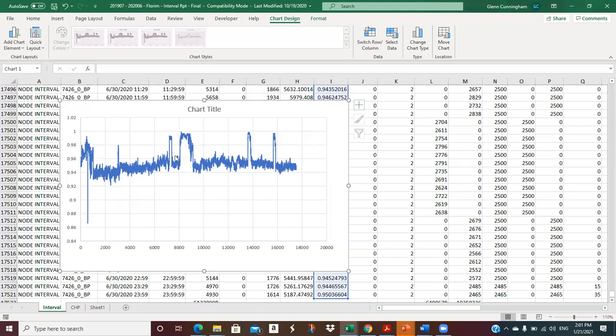And you can look across here, with information like this, you could divide it up into months and you could see what you thought their billing demand was going to be. And then you could say, well, how much do we think we could really save on this? But 95 is right in here. So they're spending most of the time right about 95. So it doesn't look like they've got a whole bunch. That's probably better than most places. If you're not doing correction, it's probably not going to be. This may be when capacitors kicked off or something. That probably is. They probably had a big capacitor bank go down for a short period, and they caught it and put it back in service.